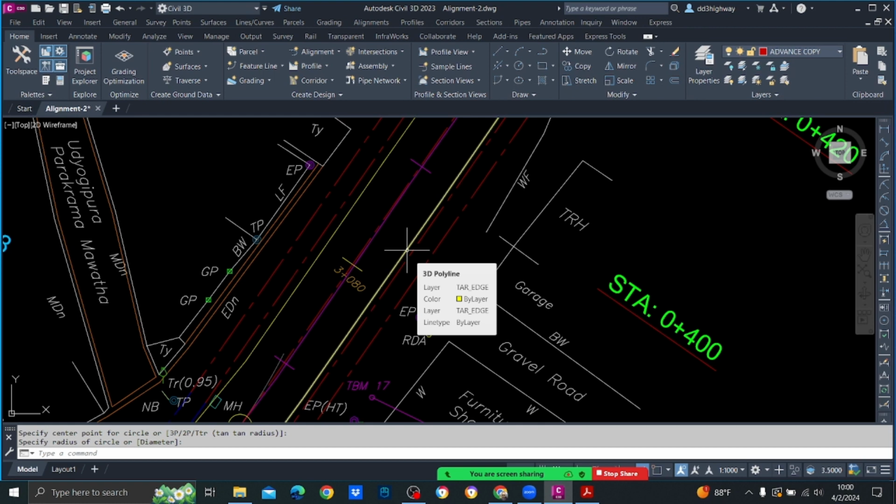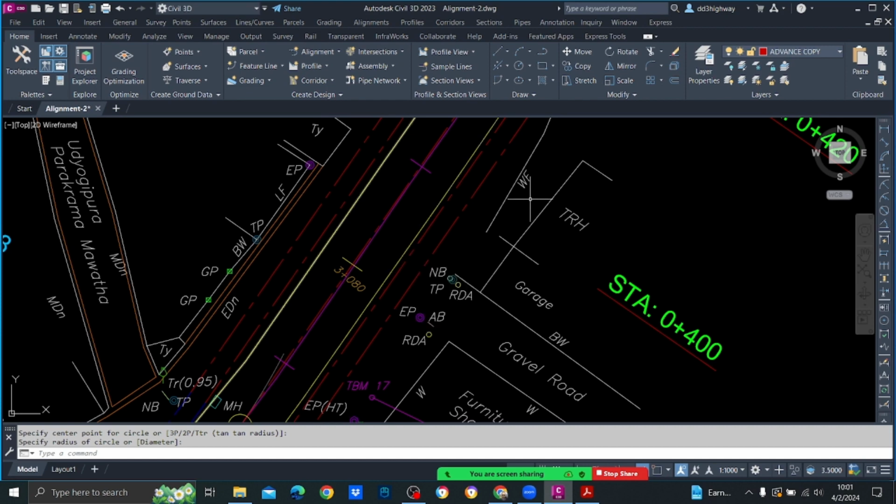It can be 100 millimeter asphalt, then maybe 200 millimeter ABC, 300 millimeter soil. Is there any recambering requirement beyond the existing road towards the widening section? No, the recambering requirement is coming only within the bounds of the existing road. Understand? Right. So we are going to model the existing road here.